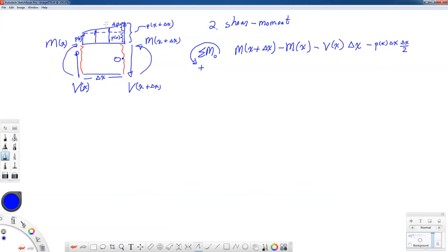And again, there will be an equivalent load from everything that's above the constant distributed portion, P of x times a moment arm distance. And I'm going to treat that in a very similar way. I'm going to write this down on the next line as a minus some other shaping constant C2 times delta P times delta x squared, and that equals 0 for equilibrium.